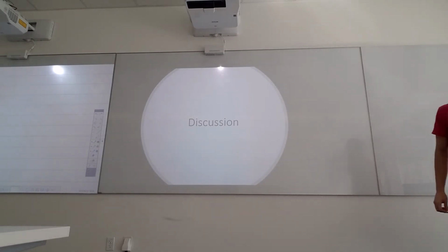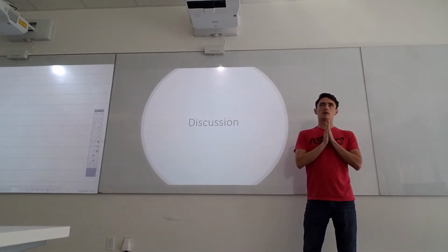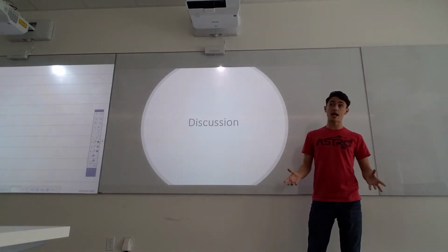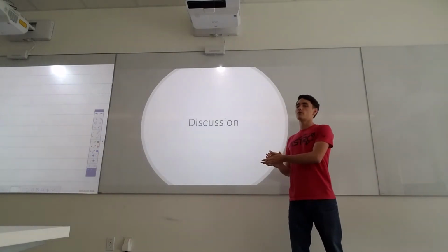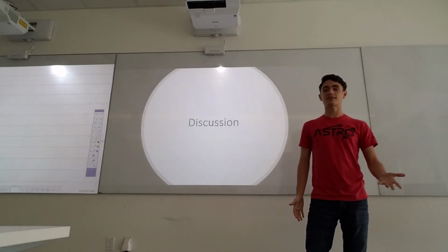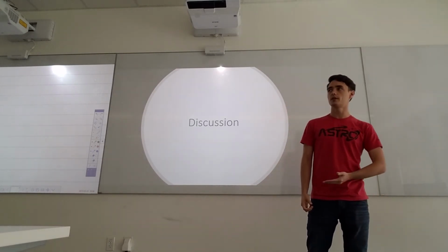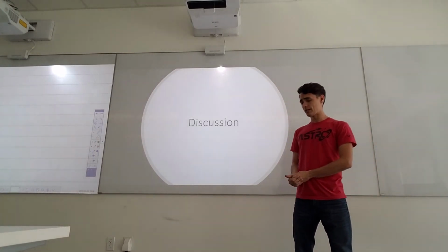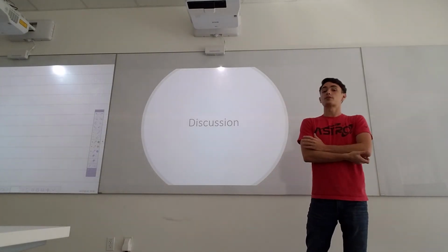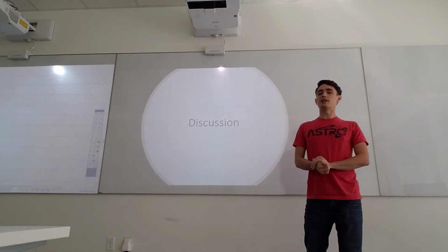So some discussion. The controllers themselves, neither is objectively bad. It always matters how, where, and why you are implementing this system. If you don't need a snappy response or something that can settle down within 10 milliseconds, then you don't need the second controller. Or if, let's say, your motor driver can't actually accept 27 volts or negative 27 volts, then there's no way you can use the second motor controller, even though theoretically it might be completely superior.